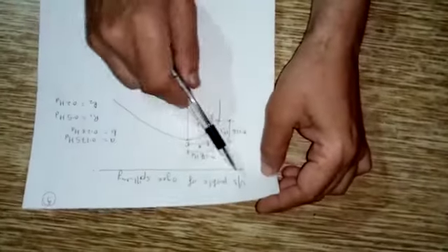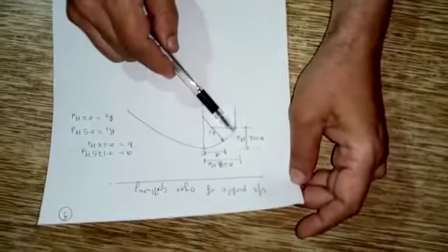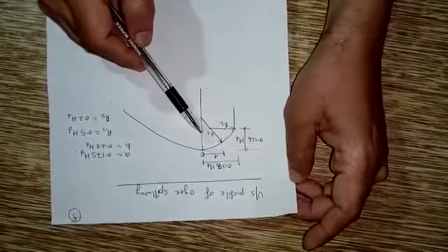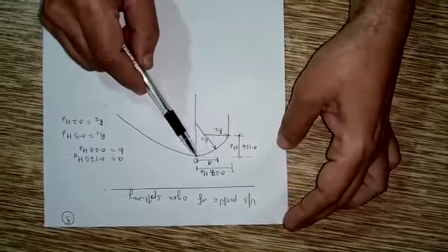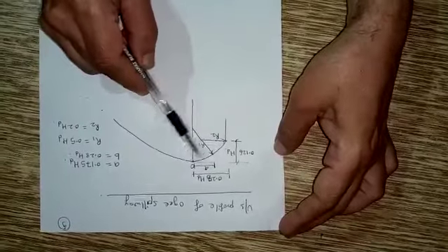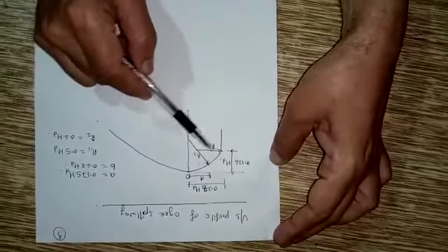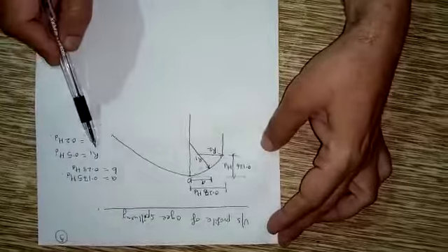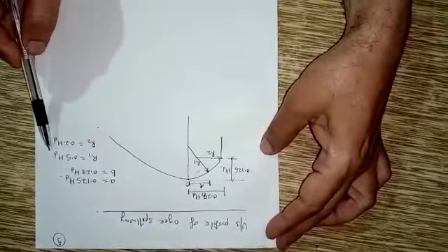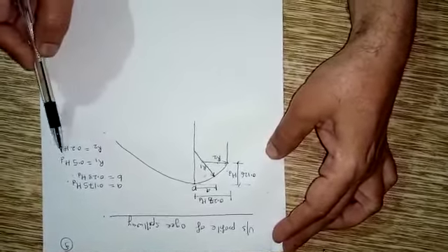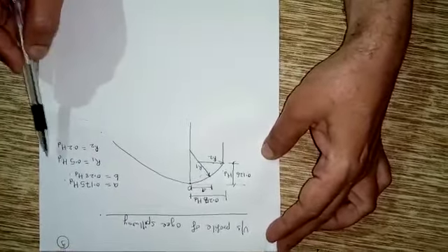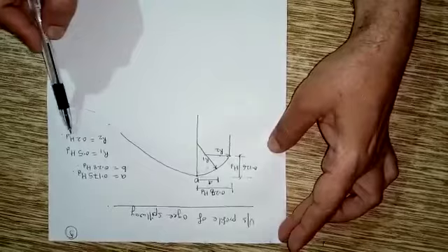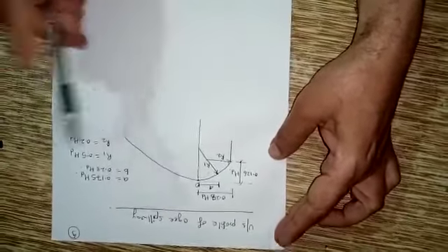The upstream profile of the ogee spillway, as per the USBR experimental studies, is in the form of a compound curve having two different radii R1 and R2. In terms of the design head HD, R1 = 0.5 HD and R2 = 0.2 HD.